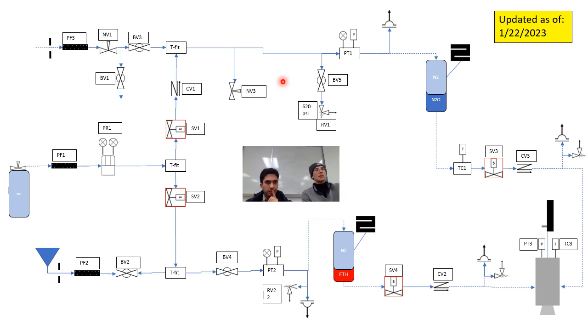So I think more clearly than "ensure nitrous oxide and ethanol are purged," which hopefully happens during the purge process, the more clear thing to say would be to ensure that the nitrous oxide fill tank, which is the separate tank that is generally stored far away and is only used during the fill process, is not connected into PF3, because we're going to be purging out and getting rid of everything that is inside of those lines, and that means we need an open hole there when we eventually start the purge process.